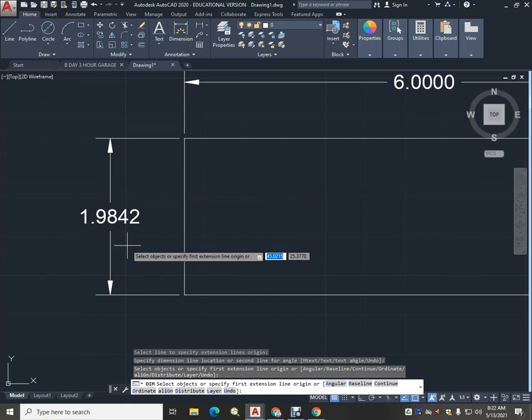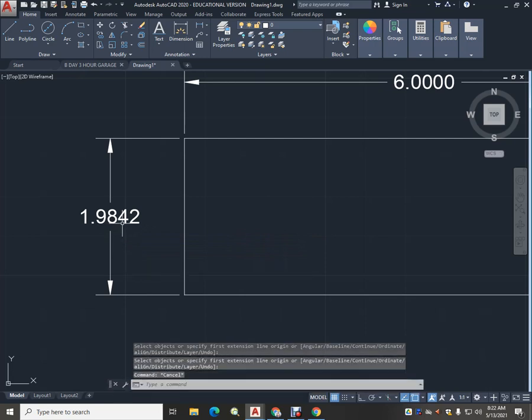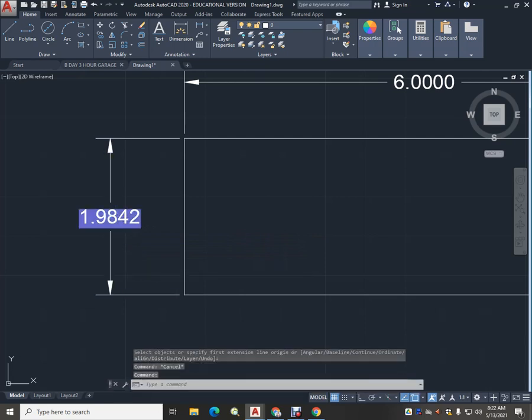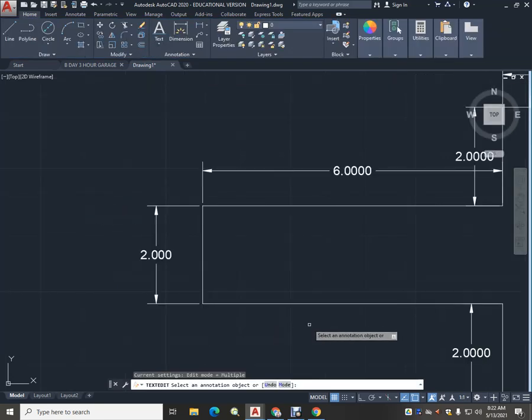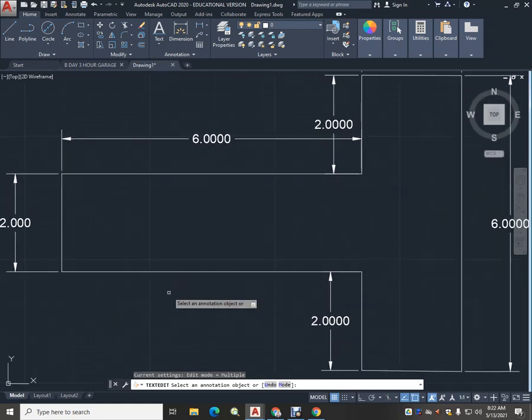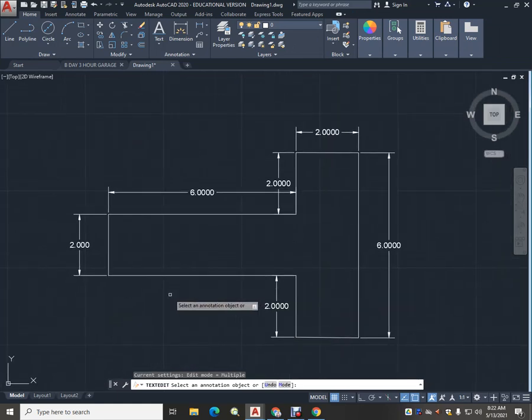That should have been 2, but when we look at it, evidently there's something amiss when we're talking about the 2 decimal places. So what we can do is, let me double click on that dimension, and I can actually retype this in 2.00, hit that delete key, and then when I click off of it, it creates that. So no one will actually know that we're just off by 2/100ths. And there would be our part.